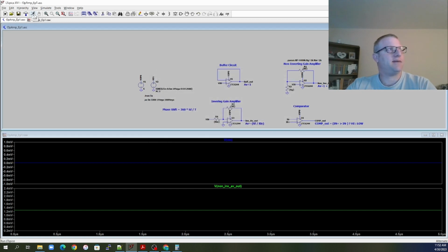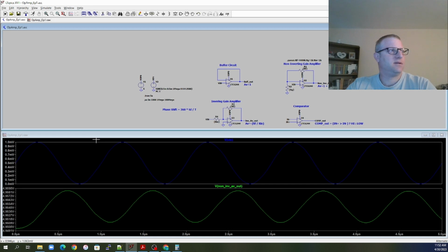Right, and now if we run that, you can kind of see we got our 1 millivolt swing like we expect, right? And our input reaches 0, that's not a problem. Our 0 point is all the way up at 4.95 volts, right? And so you can see what happens with the high gain, that voltage offset, what it'll do. So you want to watch out for that voltage offset, because depending on how big of a gain amplifier you want, it may have adverse effects.